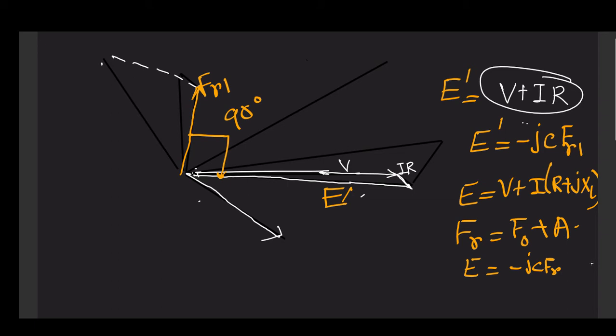Although we casually speak of it as induced EMF, actually this is also not getting induced across your winding, but we want to incorporate that leakage induced voltage in our account, so we say it's an induced EMF. It is not induced. Actually, the physical EMF drop that takes place across your circuit is V plus IR. So anyway,